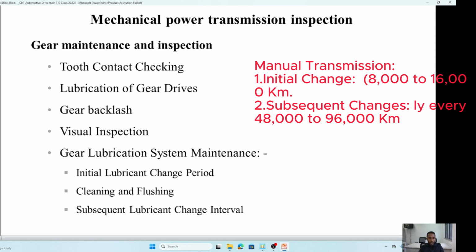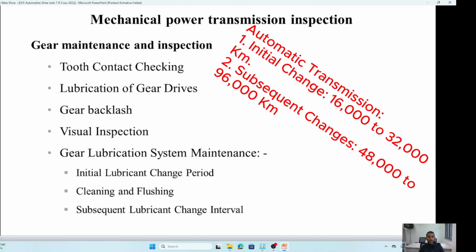So you are really assured you employ proper lubricant. When I say proper, for example, if the vehicle is manufactured in a very cold area and you bring it to a hotter area, the oil grade must be changed. Also, the second factor is that you will be assured that the proper amount and proper oil is filled.